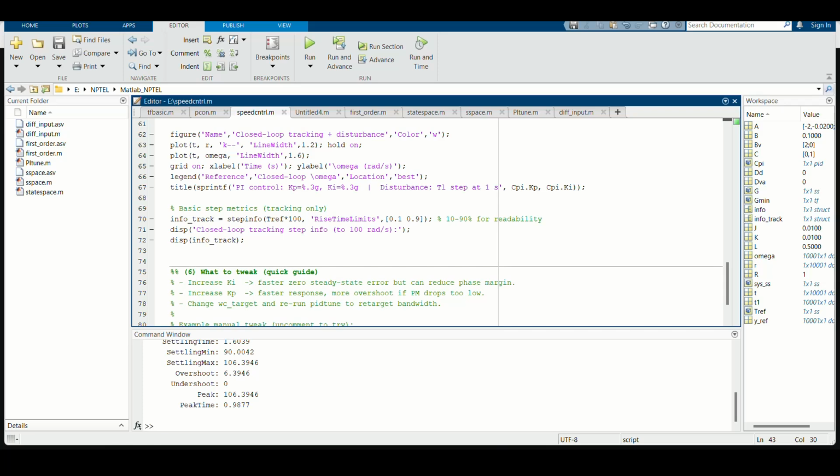Whatever gain margin or phase margin the system has, if we want a particular one, we can choose a compensator and design it by locating the pole and zero, so that the gain margin or phase margin will be the desired value. This is how the whole process can be done using MATLAB to design a complete control system for a particular physical plant to get the desired response.